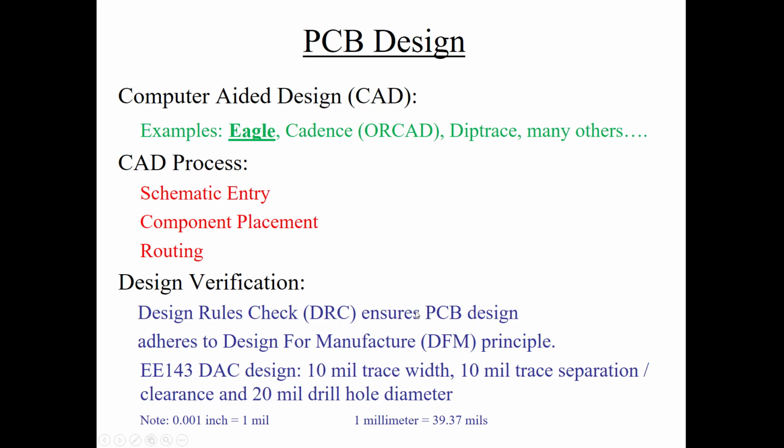Okay, because the software checks are not 100% foolproof, and you just want to make real sure, double, triple sure that your layout is actually representing the schematic, because it's much easier to make a correction before you get the board manufactured than after. So it's worth the time just to double, triple check that your layout is actually matching what the schematic is showing.